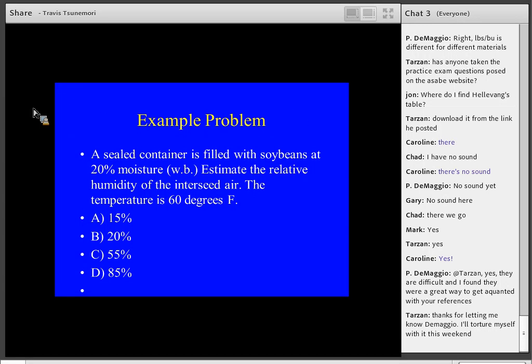85%. Second question is, and you're perhaps not being asked here, but as a good design engineer, is that a good thing or not? And I think hopefully you're thinking, maybe not so great. You really don't want to be quite that wet. 85% moisture content, could have some biological activity in there. What can you do to deal with that?